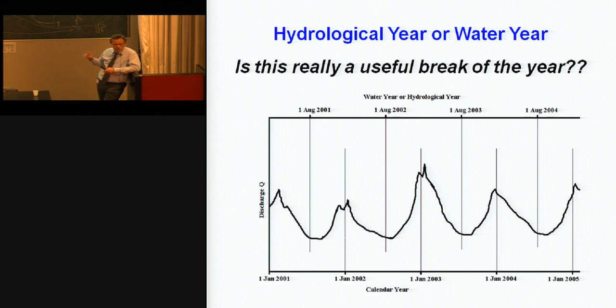Winter is not a good time to start the hydrological year on the 1st of January, because we have snow. That means some precipitation falling in November and December sits as snow in your catchment in the mountains and is not discharging until next year. So there's a dS/dt transferred from one calendar year to the next, and then it's more difficult to solve the water balance equation.